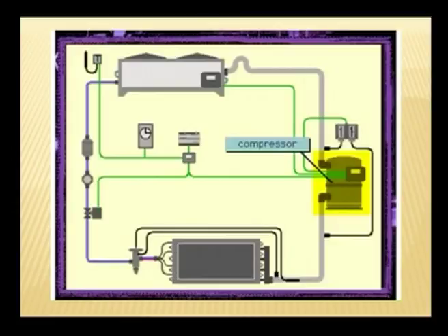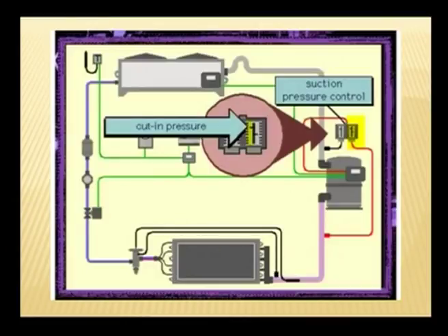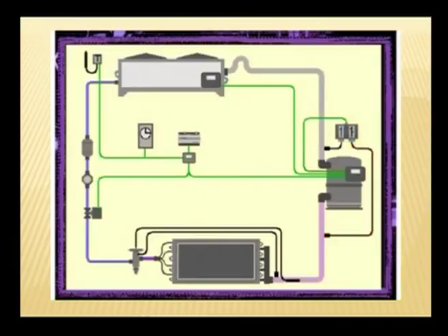The compressor starts up at the same time as the solenoid valve opens. The compressor startup is also regulated by a pressure control that measures the minimum pressure needed to be present at the compressor suction inlet. This is the cut-in pressure. This pressure is usually reached when the compressor starts up because the remaining refrigerant in the evaporator has evaporated while the compressor was off. This control is useful to prevent the compressor from starting when there is not enough refrigerant coming into the compressor from the evaporator.